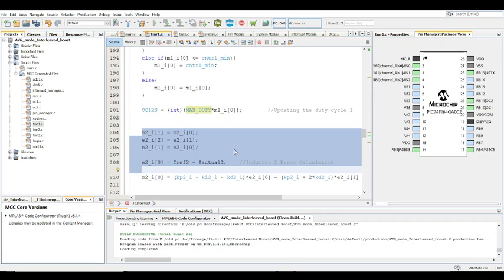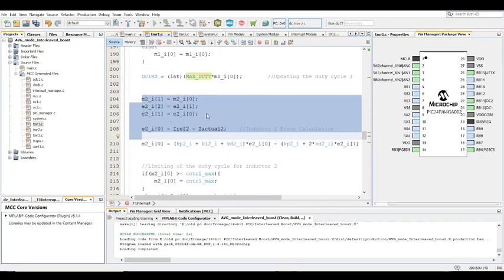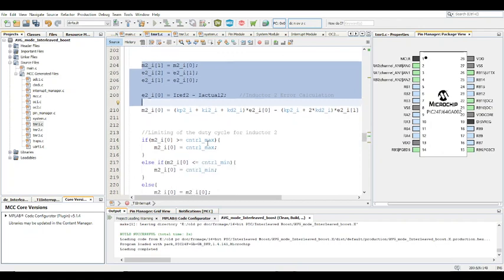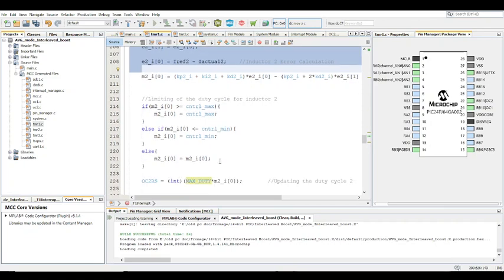So you want to sense the current going through both of them separately to account for it in control, so that the controller knows the slight changes to the duty cycle to give you the particular current that each of them needs, because they're not the same. They might be the same in a simulation, but in the real world, they're never going to be the same. And not just that, the MOSFET and the diode, even though they're from the same manufacturer, are still going to have slight differences. So you have to do the PI control routine separately to account for that.